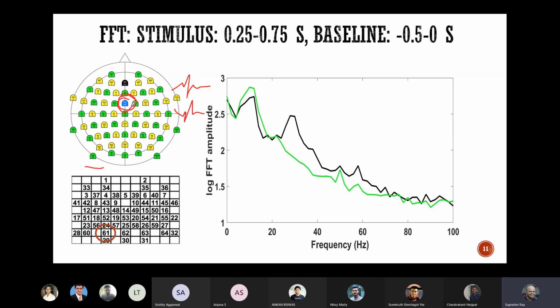Okay, so that is why when we do these recordings, you want to have the reference electrode where you don't expect too much activity. Some people, for example, use the ear lobes as the reference. So they will have the reference electrode on the two ear lobes that they will then connect and use as the reference. Some people put the reference on the forehead. People have even tried putting the reference at other parts of the body.